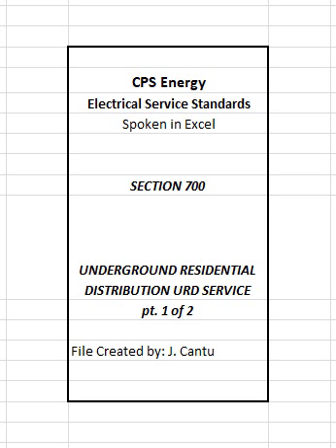703.2 Secondary laterals and enclosures. Depending on the load and locations to be served, CPS Energy may furnish and install secondary laterals and secondary enclosures between the secondary side of the transformer and the meter socket. Conduits and trenching will be in accordance with the requirements outlined for service lateral conduits and conductors, refer to Articles 704 and 705.